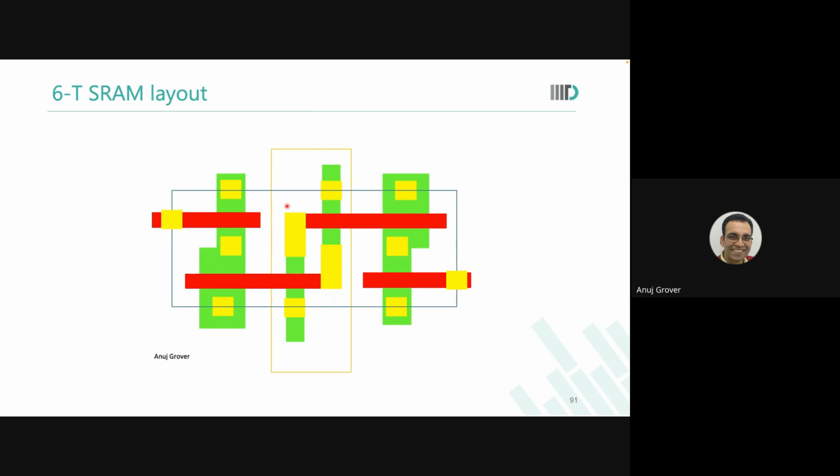However, there are very stringent rules around it because we're talking about the ductility and maneuverability with tungsten over there. But it is now more widely allowed in very advanced technologies only. So you might land on this side where you have such provisions, or you might land on the other side where such provisions are not there. Until you are sure that a LIL, that is local interconnect layer, exists, you cannot assume the contact to be stretchable. Even in those technologies where using contact or tungsten like a local interconnect is allowed, even there, the DRC for the contact is square only.